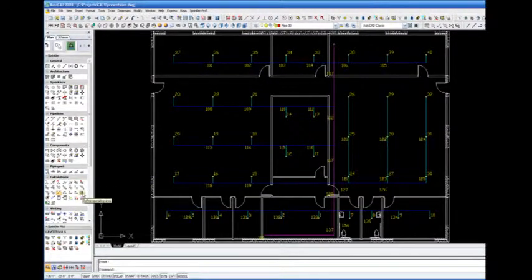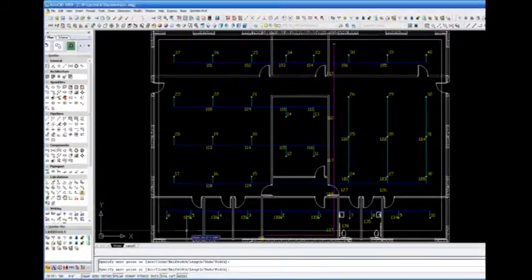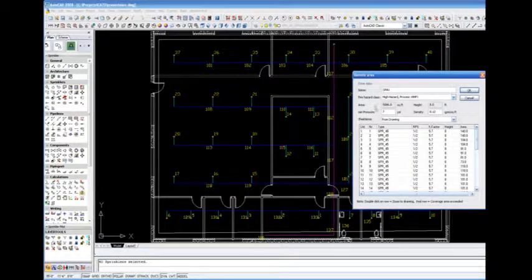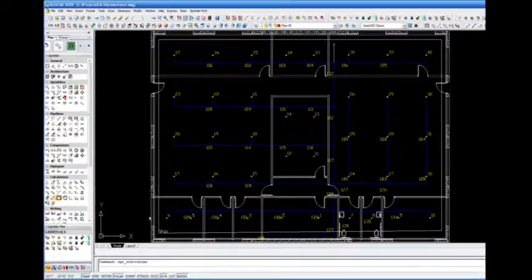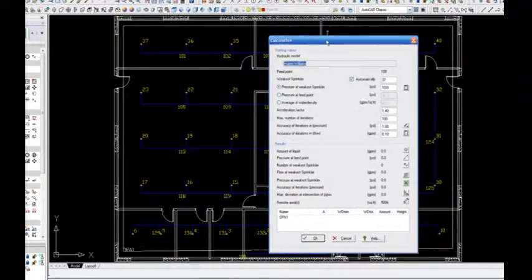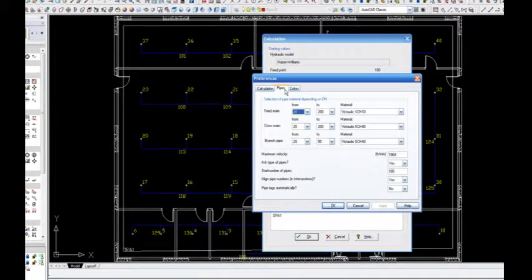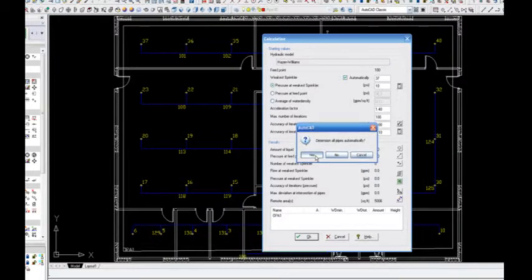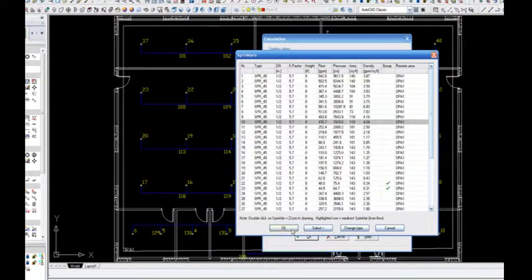Next, you define the operating remote area for the hydraulic calculation. The interconnecting pipe sections are numbered automatically. Prior to the hydraulic calculation, you have to recheck the starting values. You can modify or select the starting values indicated. Select OK. You will now see the piping lengths, fittings, type, and quantities of the fire sprinkler heads. Calculation data may be inserted onto the drawing at the location where you would like to place it. You can also export the calculation results to an Excel spreadsheet.